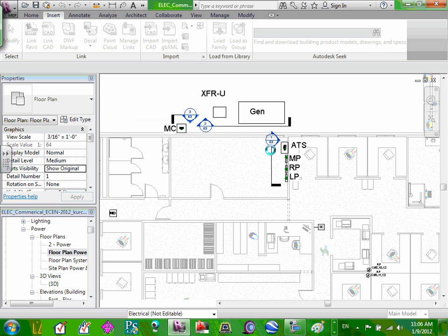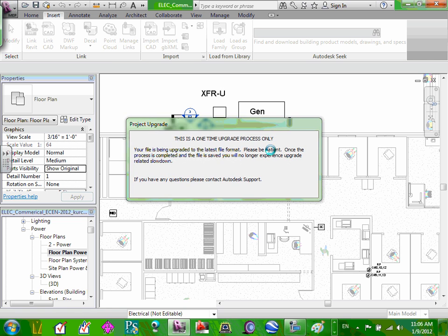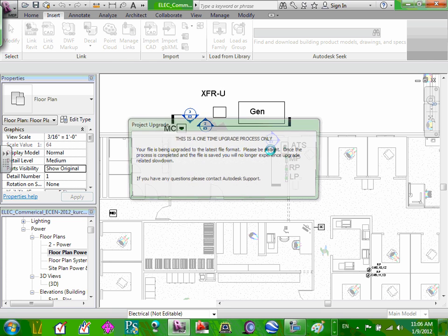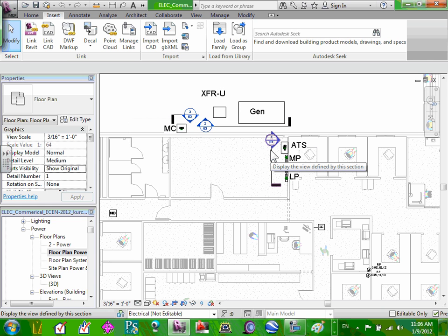Okay, so it's loading all these. While it's loading, Chris, I want to warn you, what we have just loaded is called mechanical equipment. So, common mistake number 1, Nick, from what we have done in the past. Right now, the view that I'm looking at does not allow you to see mechanical equipment because we have VV'd the mechanical equipments out. We turn them off. The first thing you need to do when you deal with mechanical equipment, because they are categorized under mechanical equipment, is that unless you have mechanical equipment picked to be shown, it will not be shown. Cool? So the first thing you need to do when you're working with especially mechanical equipment, is we're going to go to this view to show the mechanical equipment.